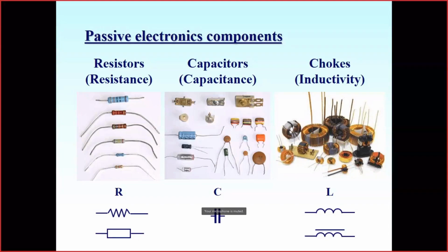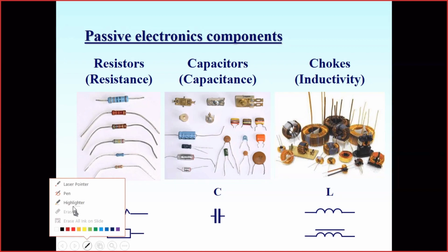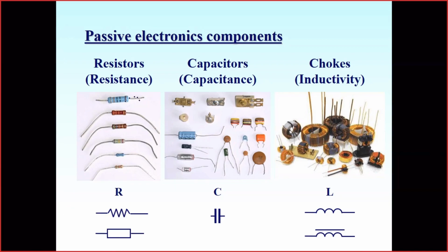Passive components include resistors, whose most important feature is resistance, measured in ohms. They give us the possibility to limit currents and to make one of the simplest but most important circuits, called the voltage divider, which sets limits on the voltages from outer sources.